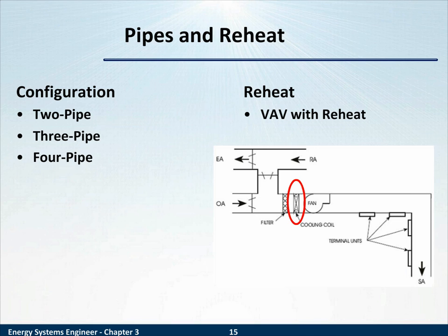2 pipes. In a 3-pipe system, both hot and cold water can come into the coil that exchanges heat or energy with the air, but then after the coil, those water streams are mixed into a tepid water. So you have 3 pipes, 2 in, 1 out. Terribly inefficient. Then there's a 4-pipe system that has 2 supplies and 2 returns.